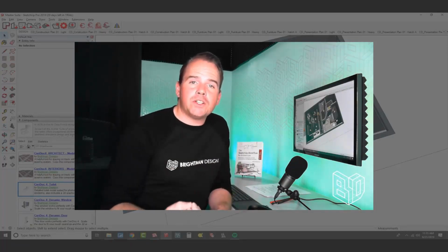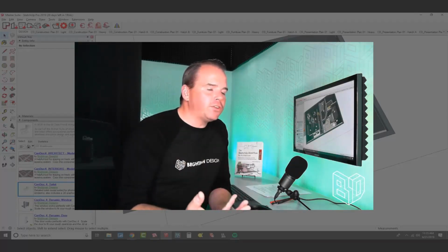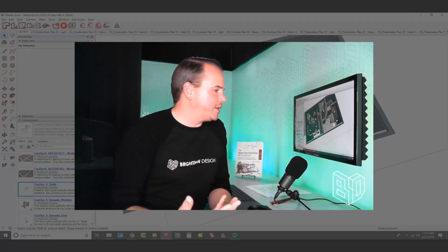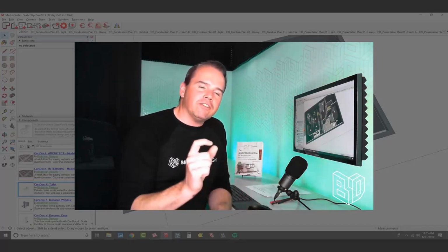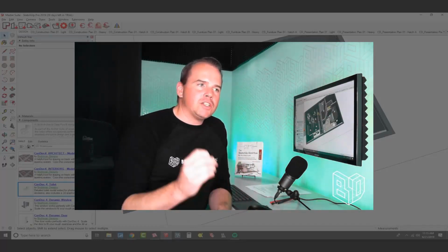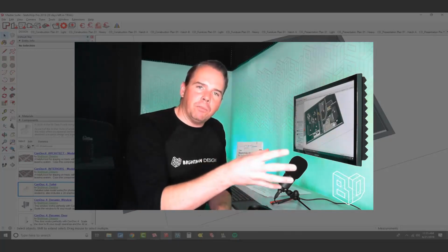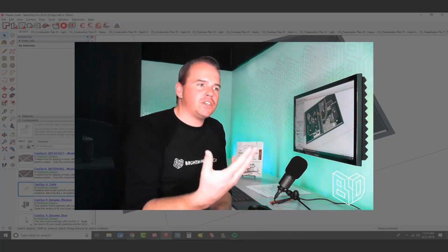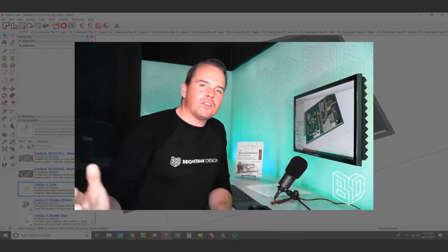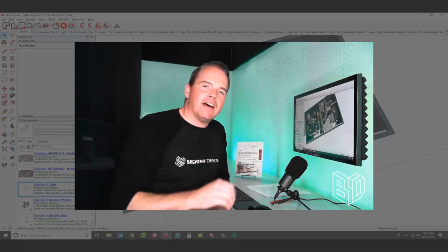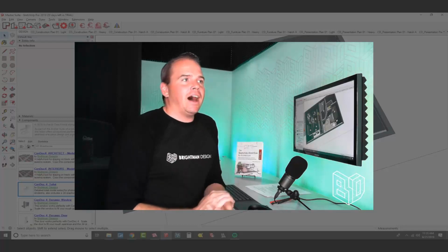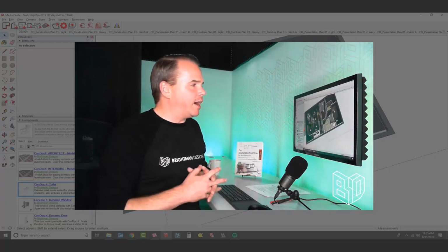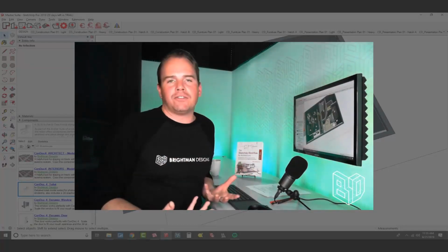Furthermore, when you get over into layout, I can also see why this myth perpetuates, because in layout, when you select a viewport, you're given a line weight input. So you get one shot at that viewport, and many people think that it's simply giving one broad stroke of one line weight onto that viewport. This is a myth. This is not true. Layout has an exceptional amount of line weights. The way it works is different, all right?